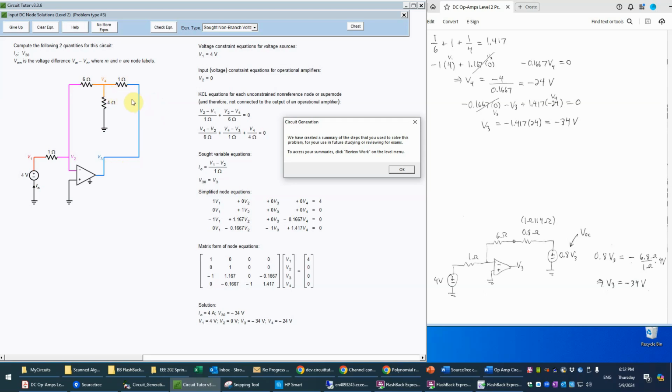Well, if we deactivate the voltage source, in other words, connect V3 to ground, then these two resistors are in parallel, and that will be the Thevenin equivalent resistance seen from the output terminals, from this terminal here and from ground. So 1 in parallel with 4 ohms, that's the product over the sum. So 1 times 4 divided by 1 plus 4 is 4/5 or 8/10 of an ohm. I've drawn that here as the Thevenin equivalent resistance, 1 ohm in parallel with 4.